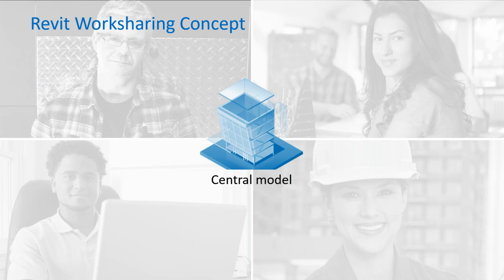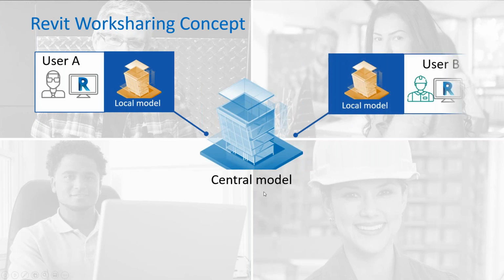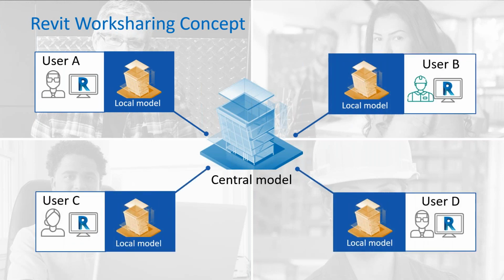It's obviously a design tool, an AEC (architecture, engineering, construction) design tool, but it's also one of the tools that allows us to design collaboratively. It means we set up Revit in something of a client-server mode. So we're going to have a central model somewhere, and that somewhere is quite important later on when it comes to BIM 360 Design. In general we have a central model, and different users all working on that central model, each having a local copy.